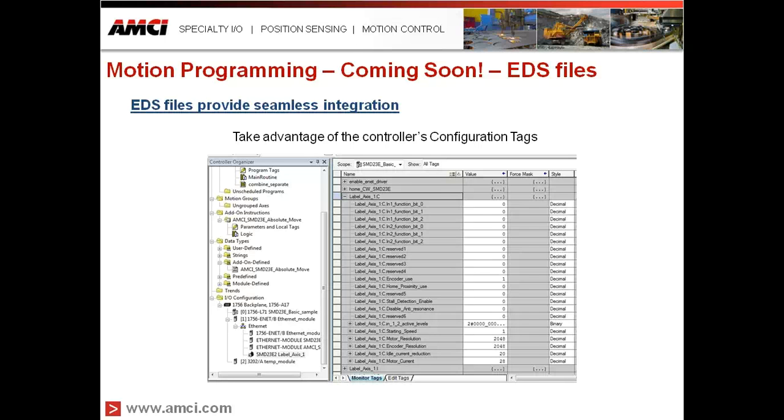That would be its own function, and entering configuration data would be its own function under these config tags. And by using the config tags, it allows us to break up that configuration data to be a little bit more intuitive. So when I open up the logic underneath that particular tab, I can see exactly what each bit and what each word means instead of having them just numbers 0 through 9. So it's a very nice feature.